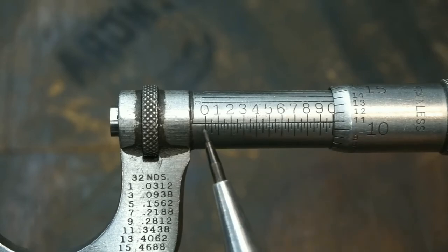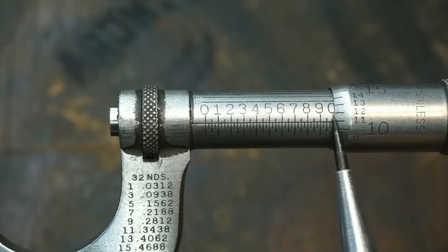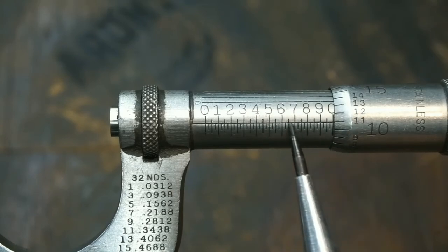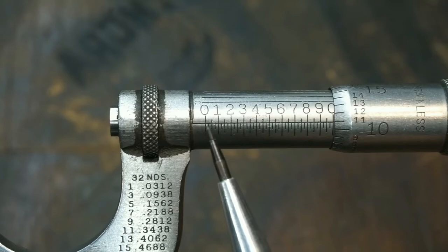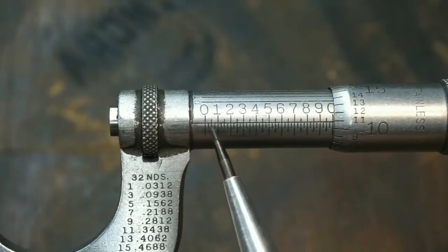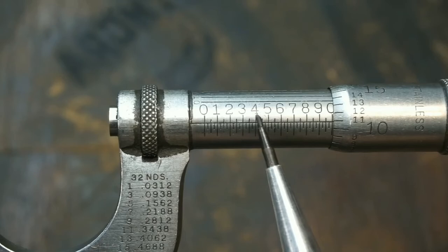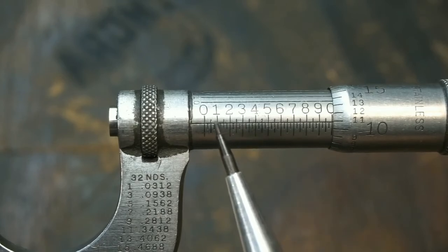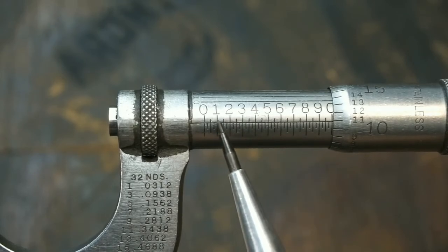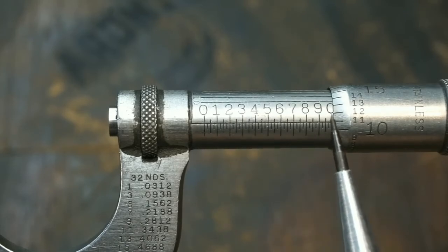And if you imagine these 2 points of reference, this 0 and 0 there, you have 1,000 equal places in between there, and that's where you're getting your measurements. So you'll notice you'll have a 1 on the top here. You have a 1, 2, 3, and so forth. So that's 100ths. So that's 100 thousandths, 200, 300, all the way up until you get to the full inch there.